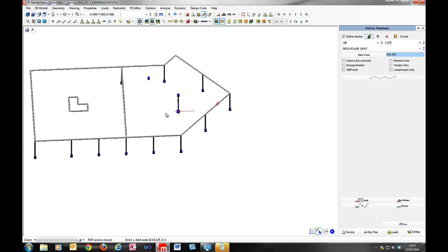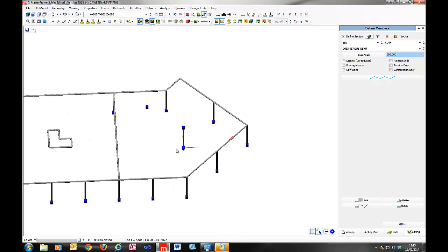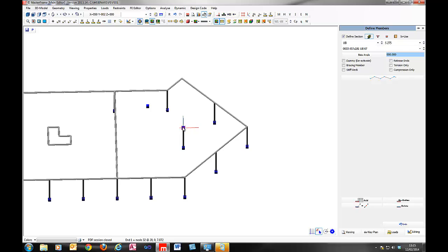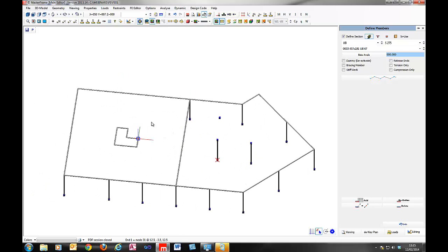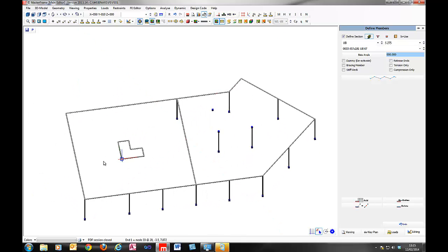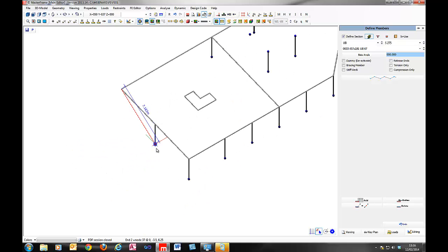Now let's just keep that a little bigger, so we can all see what we're doing. And again, just hovering my mouse over this point and this point will give me a tracking point where I want it to be in this location, moving vertically down by my column heights. That's actually all the columns on that side. Just a few more columns on this side. We'll put one at the midpoint, one at the corner, and we'll just use our tracking point there to pick up that location.